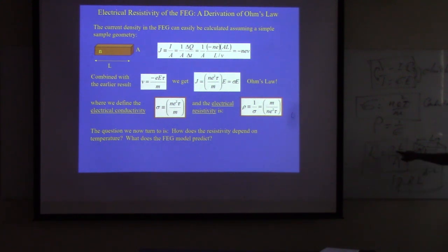That's true, because here you have width and thickness, one length dimension cancels, then you get 1, right? But if you have 2 dimensions, what happens? This is 1, right? That means rho and R are the same. Just remember, you might not see that. In the 2-dimensional case, resistivity and resistance have the same meaning. So later we'll talk about that one.